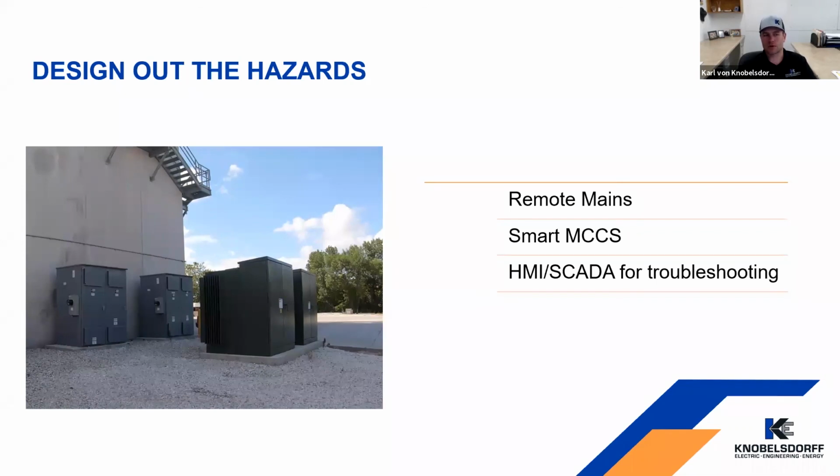Another thing that we'll do is all of your IO, let's say on a drag conveyor, if you've got a plug switch, a slack chain, a speed switch, we wire those inputs back into that bucket, and you can see those on that screen too. So again, you don't have to be in a cabinet with a meter trying to see if something's working. You can see it right from a PLC screen. And then just adding on that HMI and SCADA system, you're using that for troubleshooting and not putting your people in harm's way.